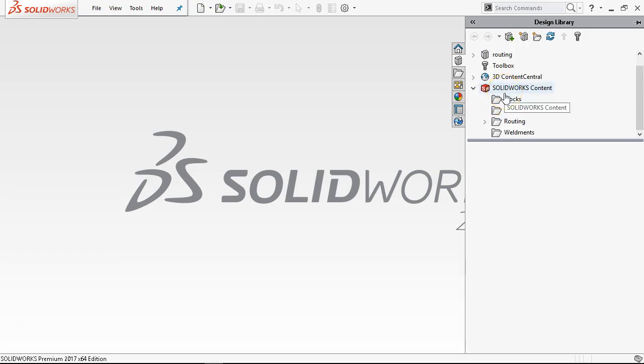Under the SolidWorks content, probably the one that's most useful is the weldments, and the initial install for the weldments. So anything that's a structural steel, structural aluminum, is going to have a profile that we're going to be able to place onto a 3D sketch and build frames, and kind of go into some of that, say kind of a secondary operation. That is a fairly limited library.